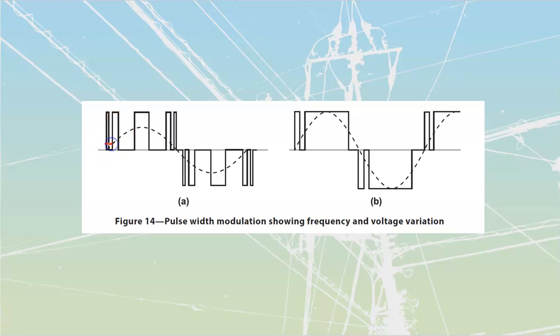If I go to average the amount of voltage, this tiny spike of voltage with this absence of voltage, I would get a very low value. All that we're doing is averaging the amount of volts that I have versus the amount of time. We will always see, no matter how much power we're trying to put out, a pulse right at the very beginning of the waveform. Doesn't matter whether we're going low power or not. If I was going for my absolute lowest power, I would have just a spike at the beginning and then nothing. And then a spike in the opposite direction and then nothing. That would give me overall a very, very low average, but I need to have that spike because that's going to give me my frequency.